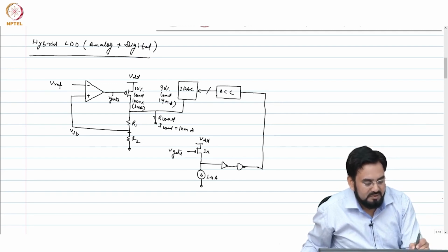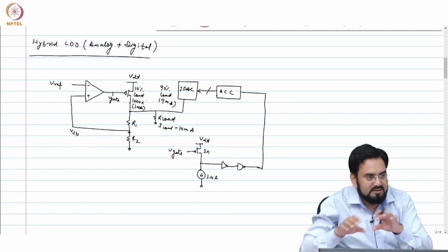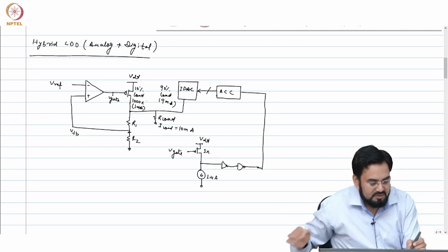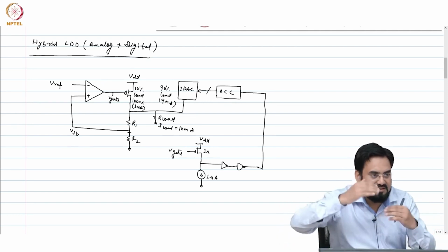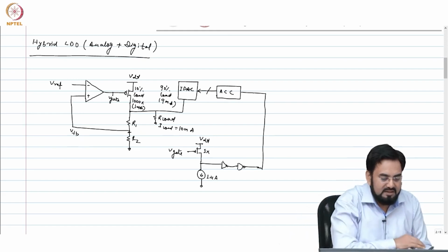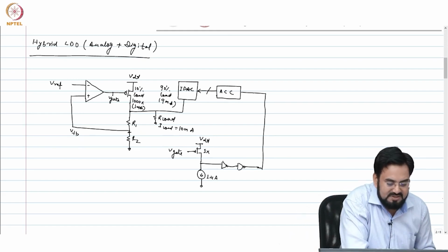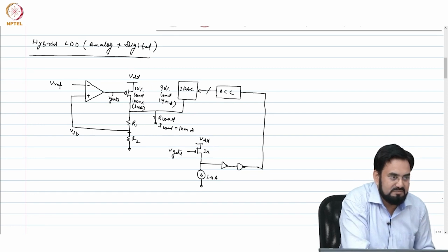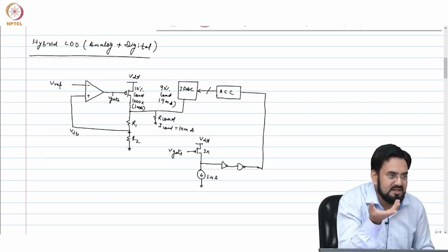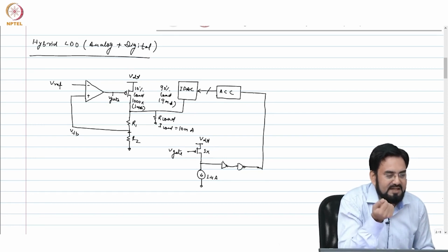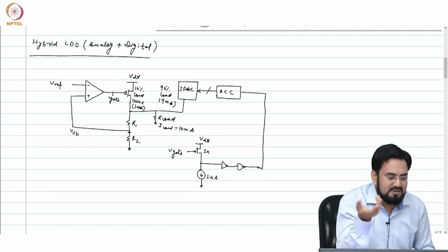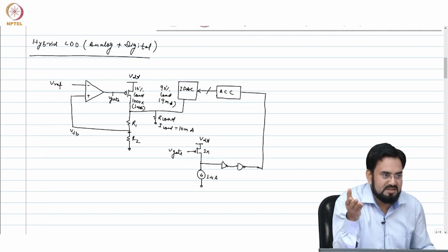This drain is routed through a wide metal, and usually the width of that metal is defined by the process. Each process has a current density for those metals, so per micron square, how much current it can carry.